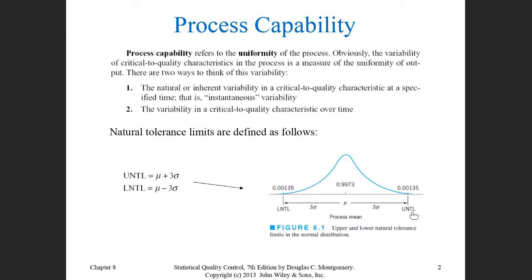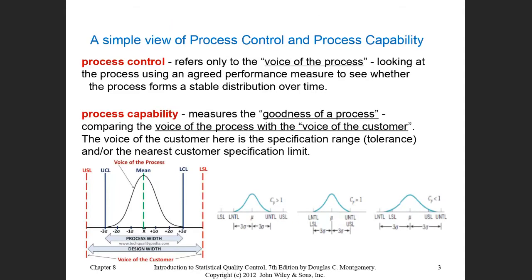These are considered to be a natural variation, and it happens in every process, and that's why, as you can see in the control chart, it is common to use the 3 sigma level or the 3 standard deviations, regardless of how the standard deviation is estimated or calculated, but it is about a natural variation. And that leads us to, okay, then what does the process capability have that is different compared to the control chart?